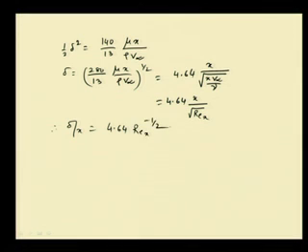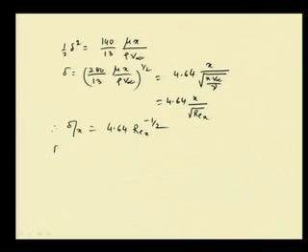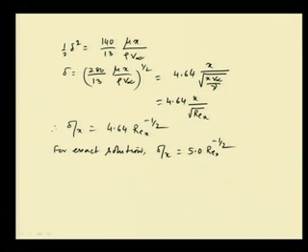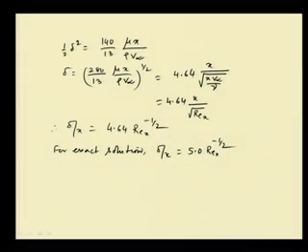Okay. And if you remember, we have already analyzed a couple of lectures before that for the exact solution, this delta by x is actually 5.0 into Rex to the power minus half. So, we can see that there is a slight variation between these two analyses. From the exact solution we get the boundary layer thickness as 5.0 into Rex to the power minus half, whereas in the approximate analysis, assuming the velocity profile, the value happens to be 4.64 into Rex to the power minus half.